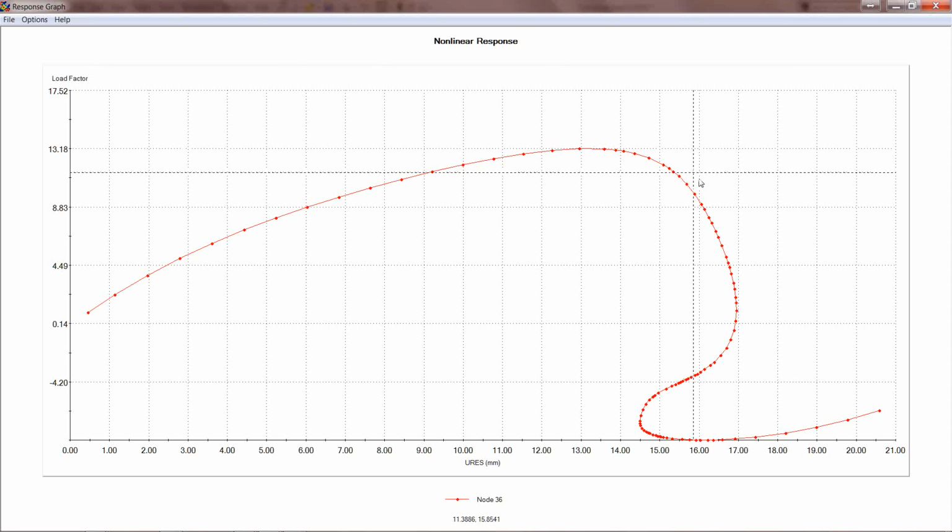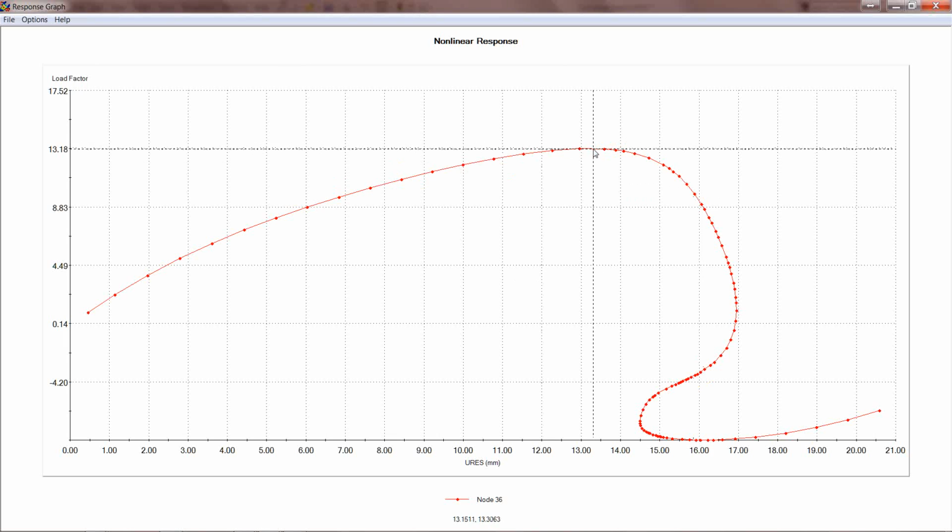The nonlinear buckling tool is able to analyze multiple buckling modes past the first buckling mode of the structure. This isn't the same as the multiple modes in the linear tool. The second, third, fourth, fifth, etc. modes in the linear tool are meaningless. But in reality, a structure may buckle once and then have a secondary buckling mode in a separate part of the structure at a later point.